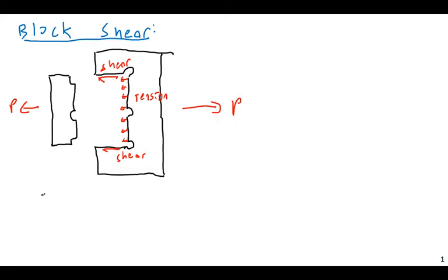Well, is this going to be a yielding or a fracture phenomenon? What do you think? Yielding or fracture? Again, yielding is where you're stretching something. Yes, this is a fracture phenomenon. Again, fracture is much more critical than yielding. With yielding, you're basically causing excessive deformation. That can be detrimental, especially if it's going to cause bricks to crack or drywall to crack or window frames to buckle or something. That's not a good thing, but it's not catastrophic. Fracture is catastrophic, so we use a lower resistance factor here. So this is going to be a fracture phenomenon.